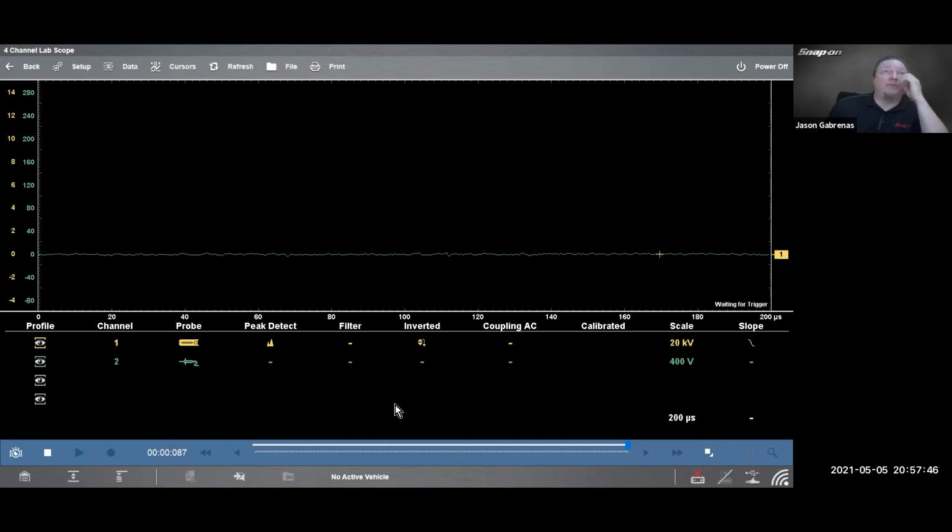Okay, so why do the red and blue test leads for the Veris not include a ground lead? I know the green and yellow leads do. So the yellow lead has 2 straight ends, right? So that is your actual ground for the scope. On the other end, you're going to have a right angle with a flat top and a right angle with an extra little thing coming off the top. That is for stacking the ground.